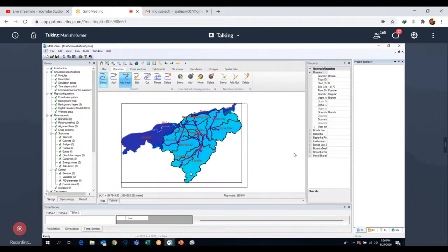If you click on any part of your DEM, it will give you a path from there to the downstream-most point, showing where this river is going. If I select here, and I have a DEM in the background, you can see that it can trace a river down in the downstream direction.